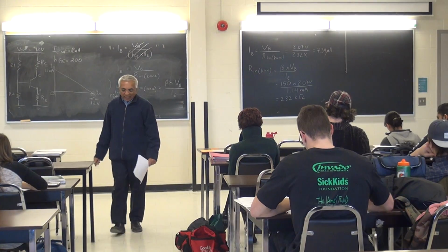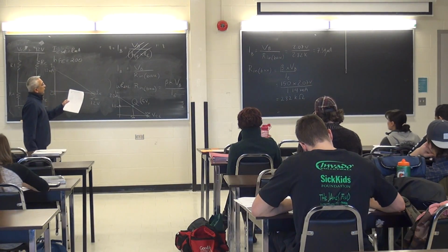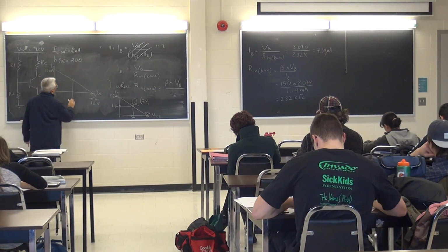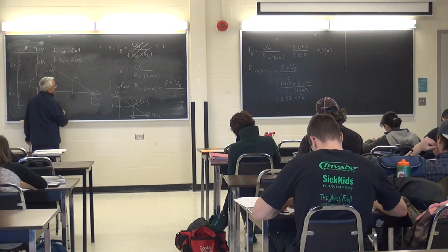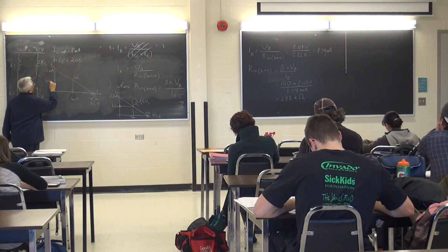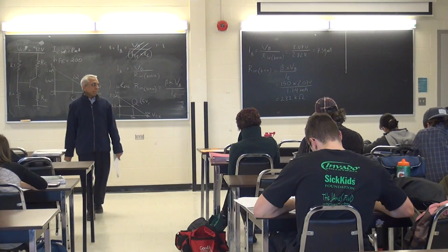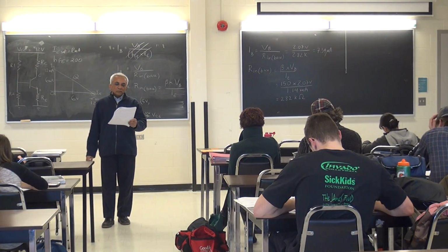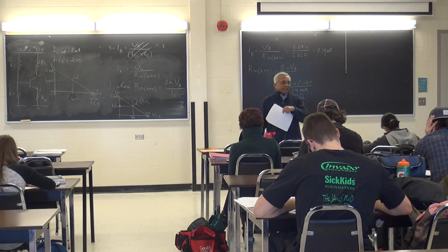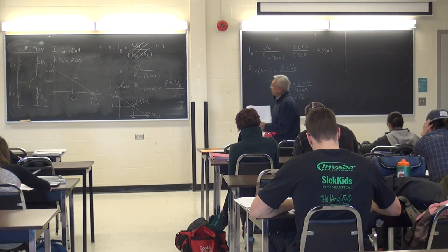And somewhere along that line, my transistor is going to operate. I'm told midpoint bias. So right in the middle. How much for VCE? 6. How much for IC? 6. You see where I'm getting those numbers? Midpoint. Okay, so given the Q point, I'm going to be working backwards. I'm going to find out RC, RE, R1, R2.